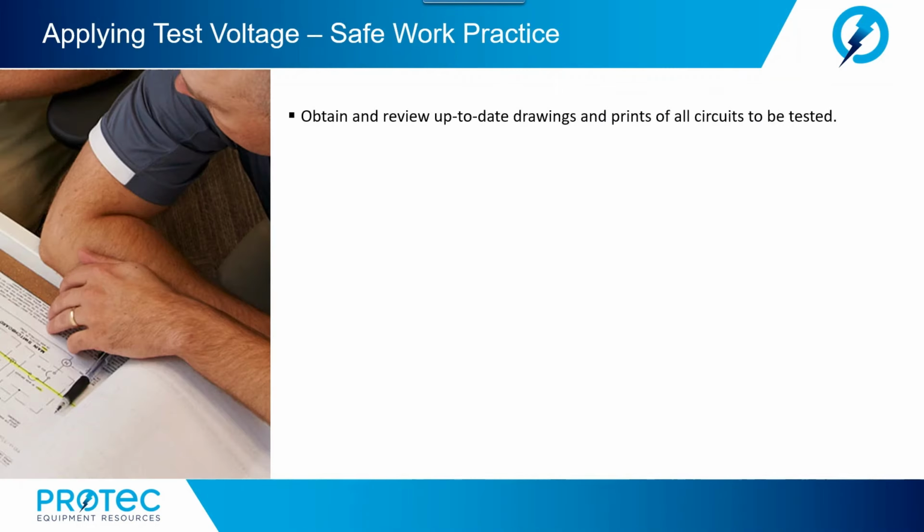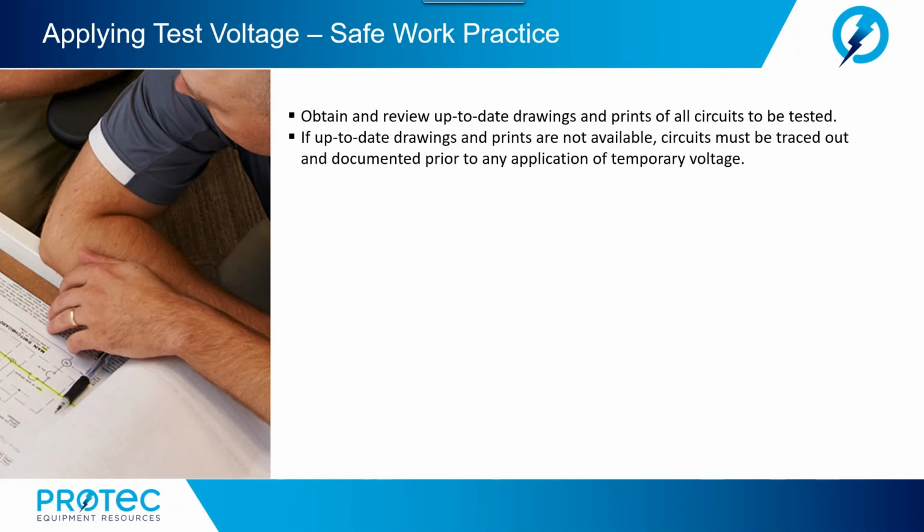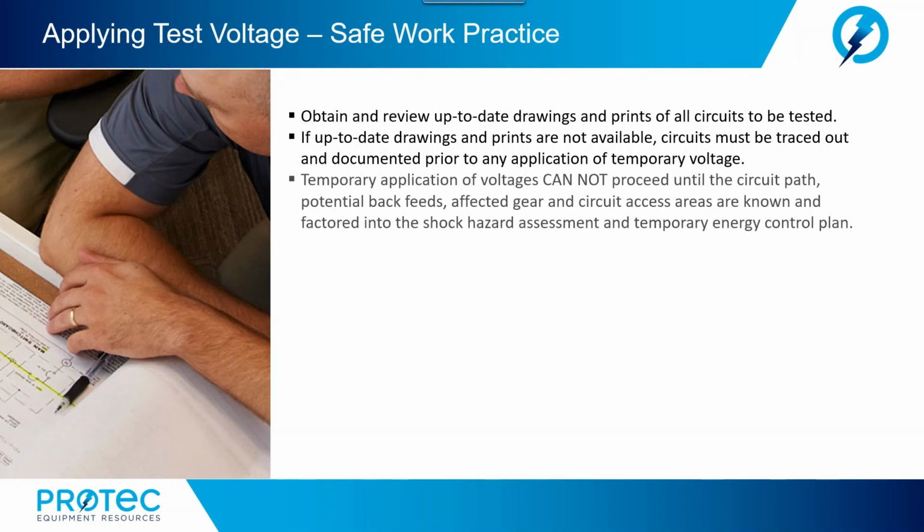Now, our safe work practices when applying any type of test voltage to a specimen. Obtain and review up-to-date drawings and prints of the circuits to be tested. If up-to-date drawings and prints are not available, circuits need to be traced out and documented prior to any application of temporary voltage. Bottom line, you've got to know where the voltage is going.